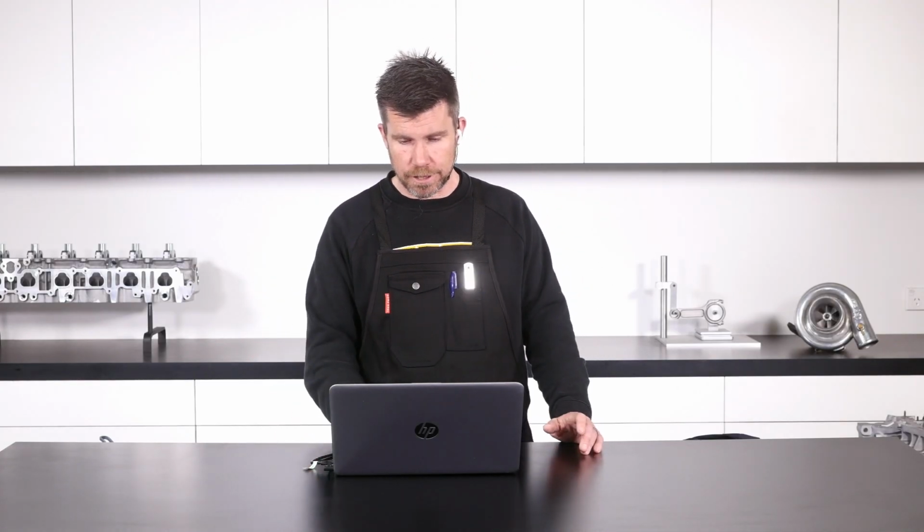With a twin scroll versus a single scroll, irrespective of the exhaust back pressure, we do tend to find that for exactly the same A/R housing, the twin scroll housing will provide better response. So there is a consideration there. All other things being equal, even for a lower exhaust manifold back pressure value, you're likely to find that a twin scroll housing will actually build boost quicker than a comparable sized single scroll housing. Of course, that's why people go that way in the first place.